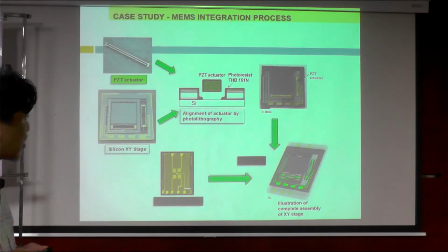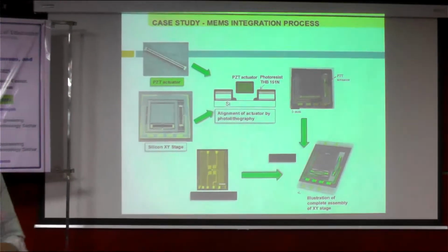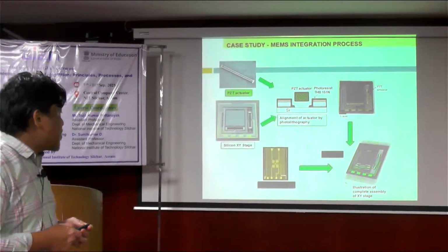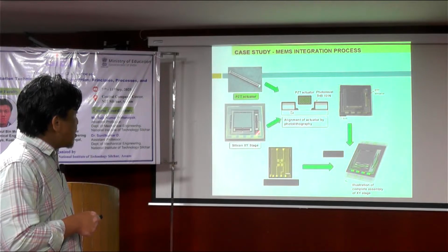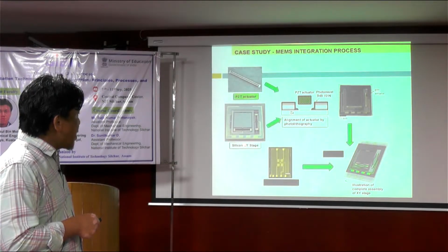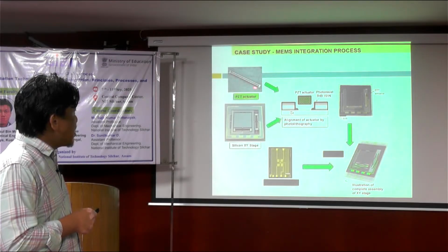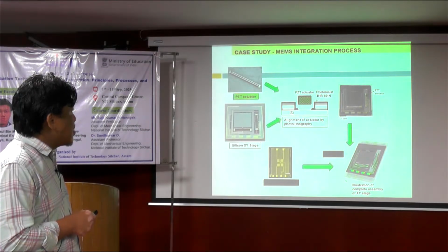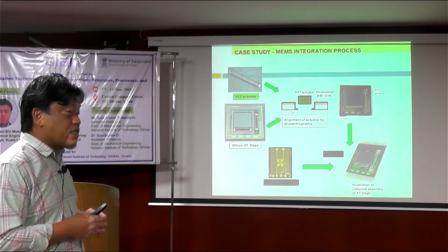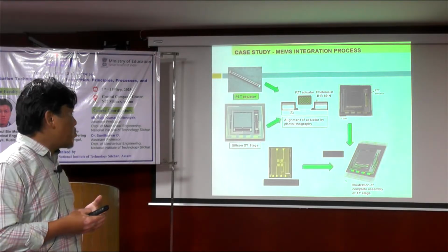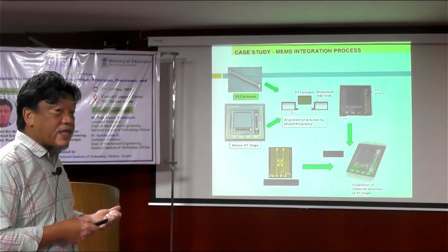And another, I would like to also introduce a case study of this kind of integration of MEMS devices. So in this case, we have this kind of silicon microstage, to be integrated with a piezoelectric actuator or PZT. This integration is a process that might be a little bit detailed in normal cases, but it's not at the chip level, this is at the MEMS device level.